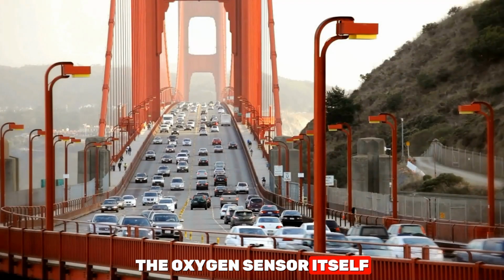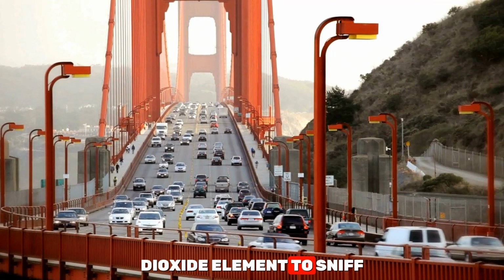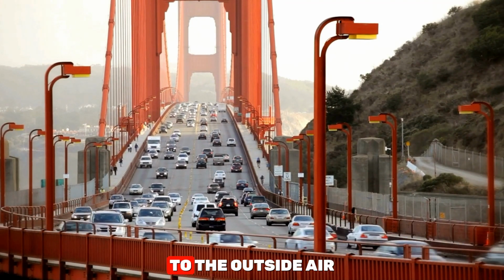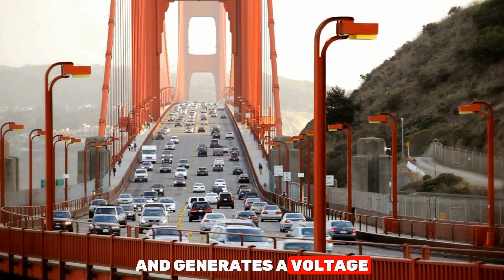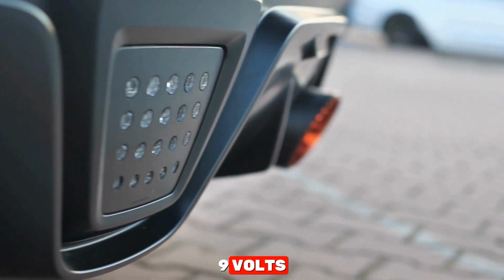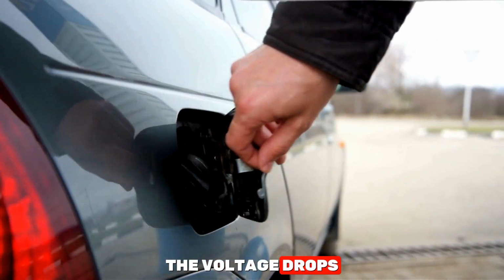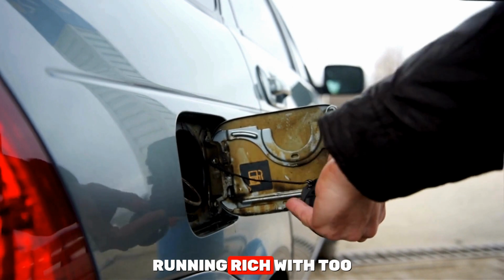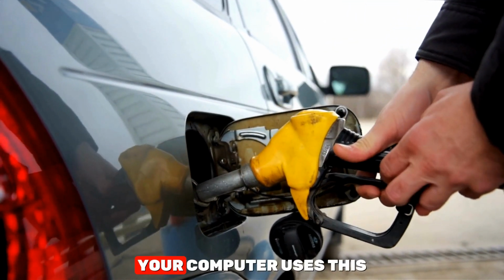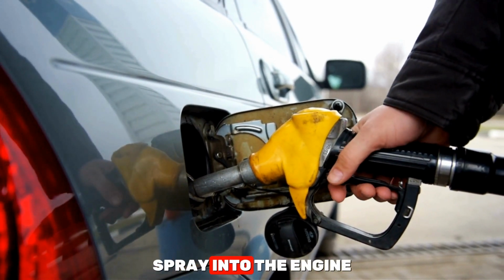The oxygen sensor itself is a critical component that uses a zirconium dioxide element to sniff your exhaust fumes. It compares the oxygen levels in your exhaust to the outside air and generates a voltage signal that bounces between 0.1 and 0.9 volts. If the engine is running lean with too much air, the voltage drops, and if it is running rich with too much fuel, the voltage spikes. Your computer uses this data to constantly adjust how much fuel to spray into the engine.